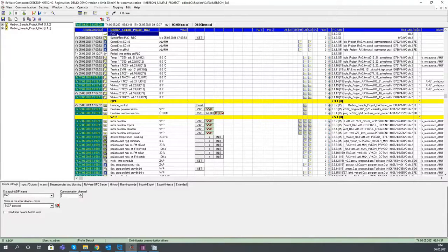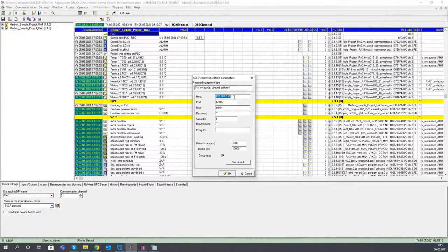And then, as soon as we start the communication again, without stopping it first before the editing, it may happen that the values which are communicated from the runtime to this data table are funny, like hundreds of centigrades, temperature, and so on. And this can be prevented, this can be fixed by deleting a particular file, but this is what I will show you later. So now let's just keep the rule that before we edit the file, we stop the communication, which is the situation right now. So the communication is stopped and the file has been edited.